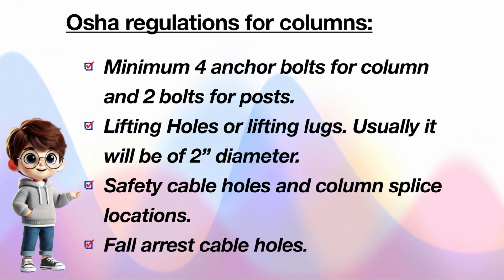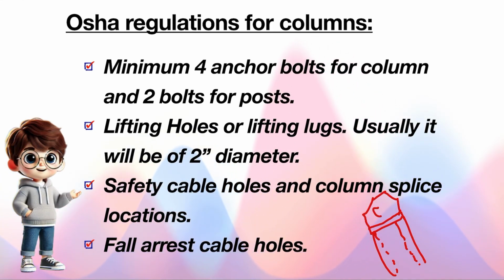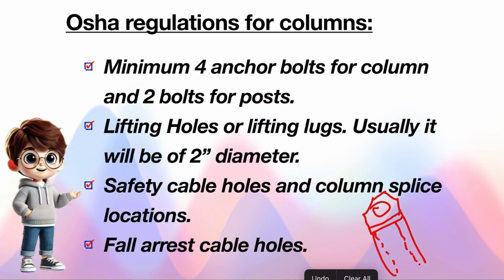In the same way, if the column is an HSS column, you can't provide a 2-inch diameter through hole in the HSS, right? It would be very costly for fabrication. So instead of providing a 2-inch diameter through hole in the HSS, we'll provide a cap plate, and then to that we'll provide a lifting lug, which will have a lifting hole.